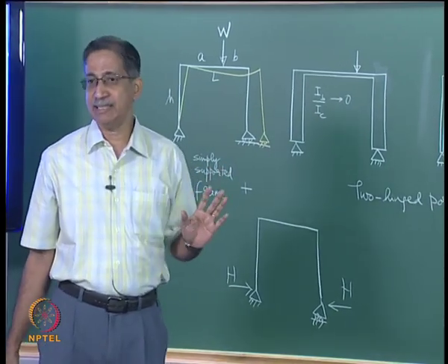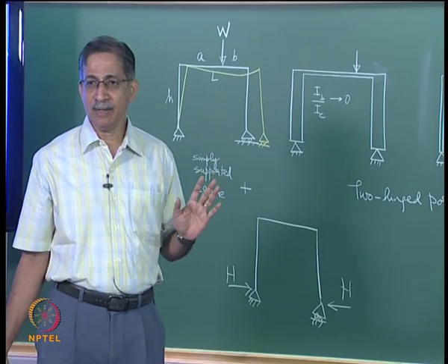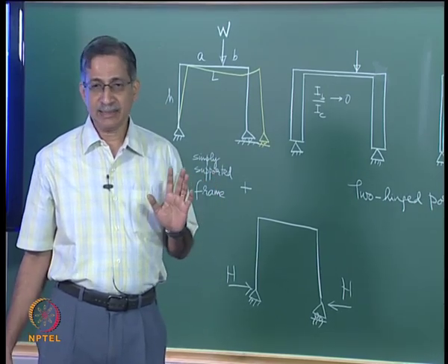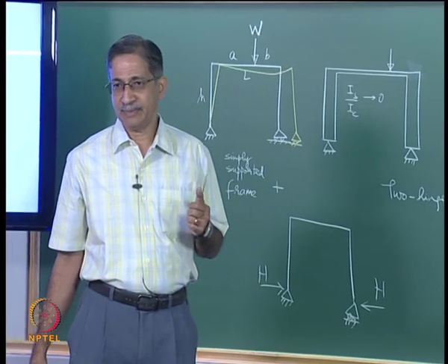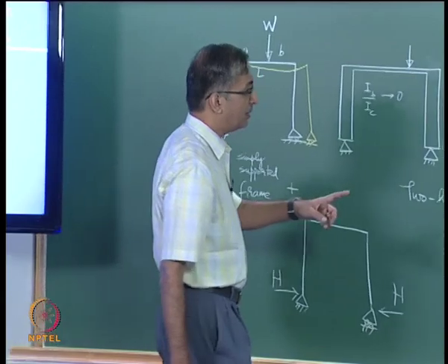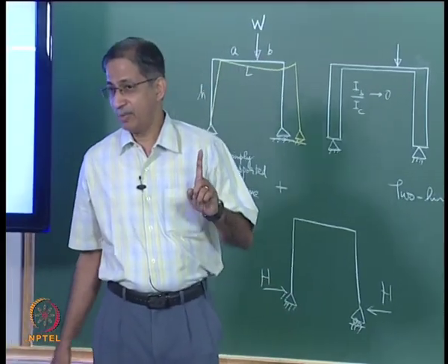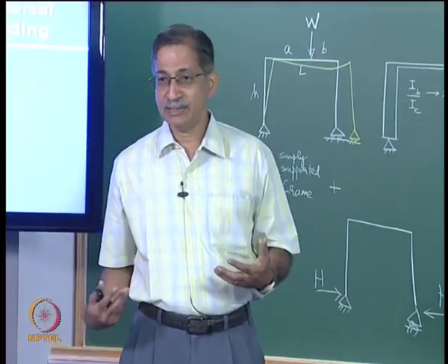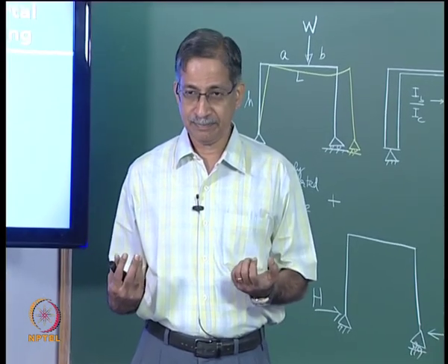It is statically determinate. The statics do not depend on the member sizes, the material property and all that. It is a straightforward equilibrium calculation. But the response of the portal frame, which is 2 hinged, does depend on IB and IC.